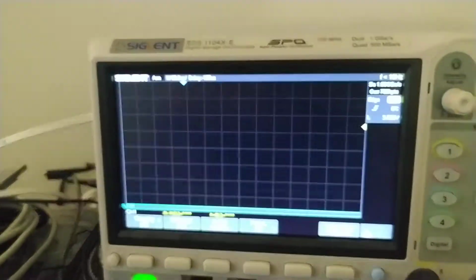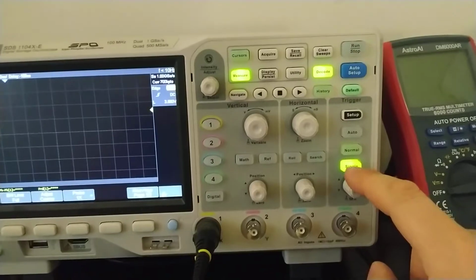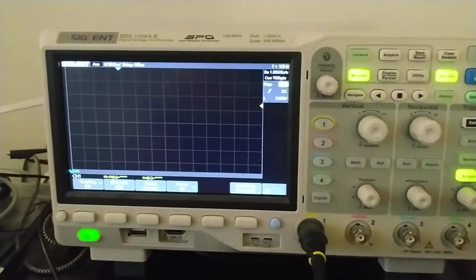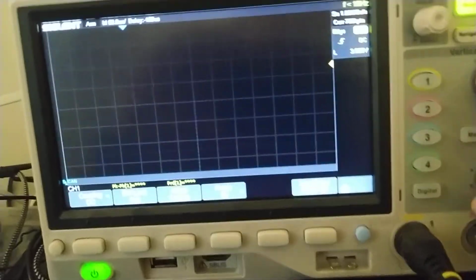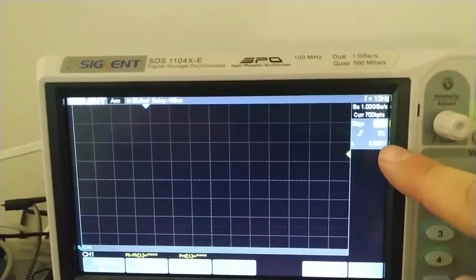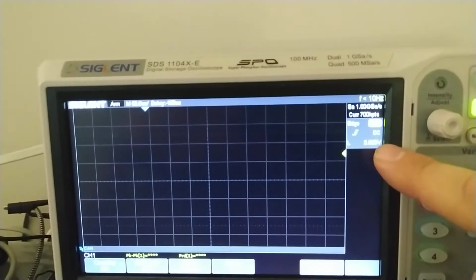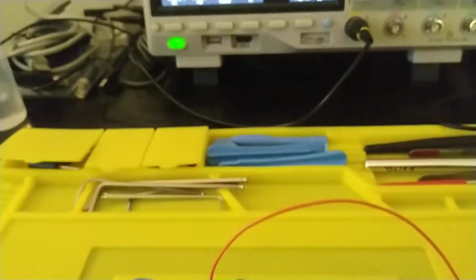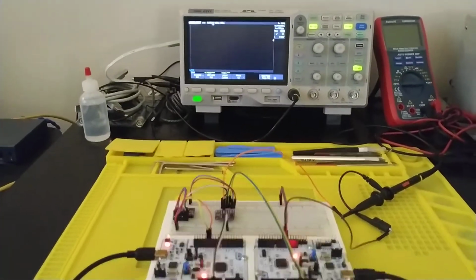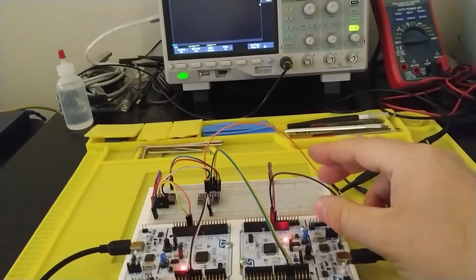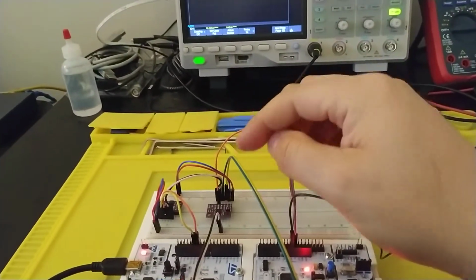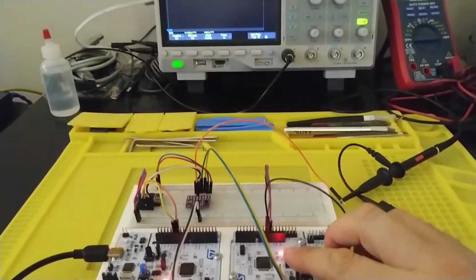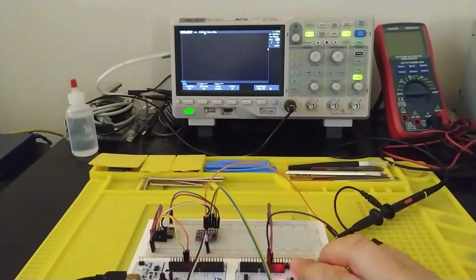What I'm going to do now is a single capture, with the settings that I was showing before. I'm at minus 3.2, and my trigger is about 3.5, 3.6 above 3.2 volts. I'm on the transmit side, connected to the transmit transceiver, and I'm going to press the blue button.